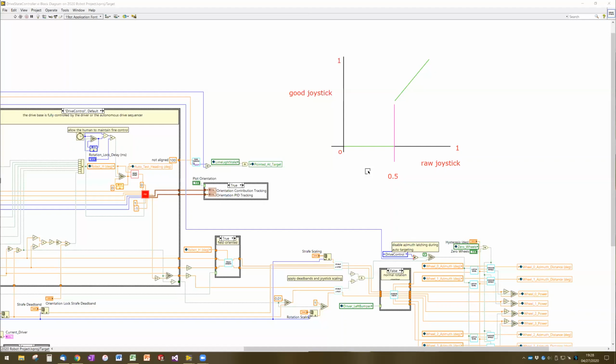Continue. So if we've got a much larger deadband, and so our function looks something like this, what do you think would happen? It wouldn't allow for them to get small increments or just a little bit of movement. Yeah, so it'd be very hard or impossible for them to go at low speeds. They would literally go from 0 to 50% power. So there would be this very steep jump as you come out of the deadband.